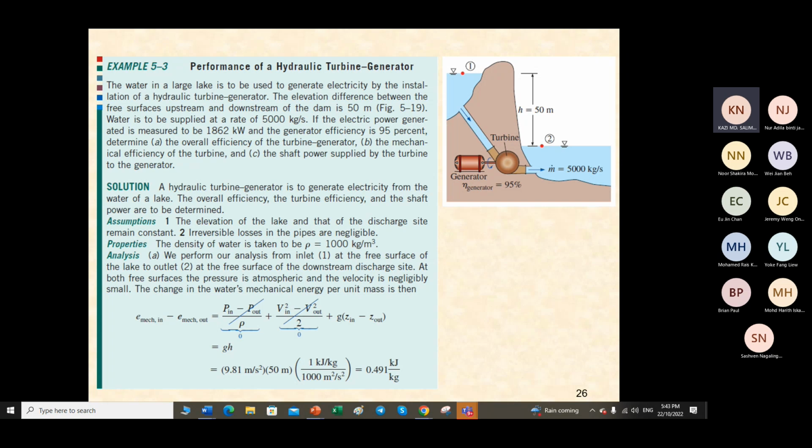In a hydroelectric power plant, people can pump the fluid during the lean time, wherever the electricity is available at a low price, to the upper reservoir, and when the load increases, that stored energy can be used for energy recovery. This way, some sort of benefit can be obtained from this energy storage principle.